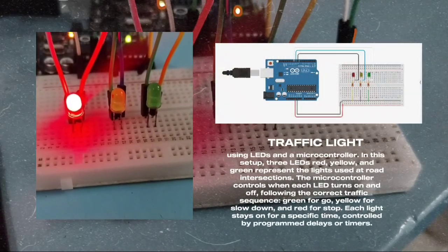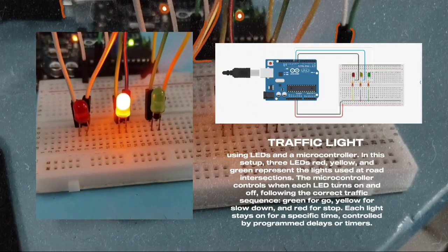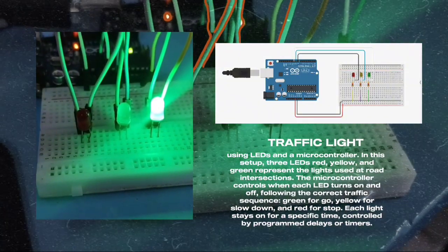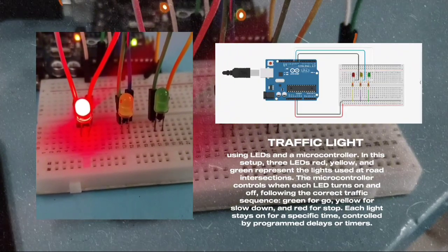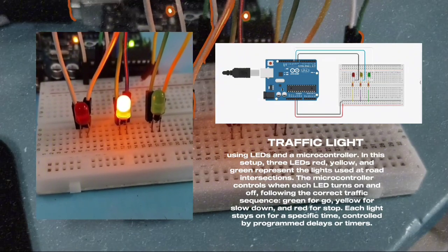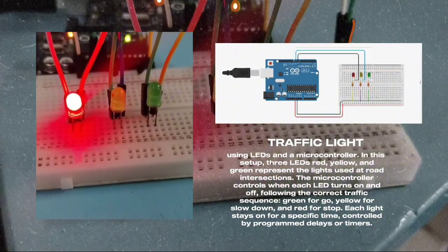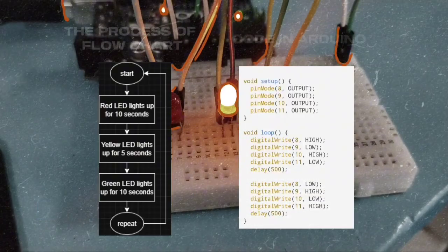Second LED task is the traffic light simulation. Using LEDs and a microcontroller, in this setup, 3 LEDs, red, yellow, and green, represent the lights used at road intersections. The microcontroller controls when each LED turns on and off, following the correct traffic sequence: green for go, yellow for slow down, and red for stop. Each light stays on for a specific time, controlled by programmed delays or timers.